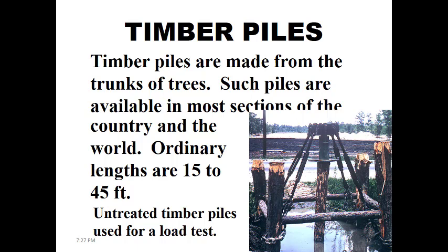So for this purpose, when we have to test timber piles in the media at a construction site, there is no need for using the more expensive option of a treated timber just to check when you reach the resistance that you are looking for to support the weight of the structure itself. So in that particular case, it can rely on this untreated option, because all we need to know is if the media is supporting the load that we plan to place over it.